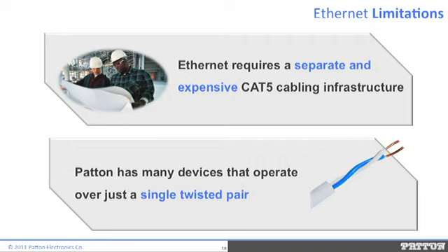The second, which is no small task, and I believe Nathan talked about it a little bit earlier, is Ethernet is not able to operate on the same cable plant. Most other legacy communications equipment was operating over plain old telephony grade wire. Ethernet really requires Cat5 cable or greater to operate properly. A minimum of 2 pairs is required for standard Ethernet data, and 4 pair if you run PoE Ethernet. The cost of rewiring the cable plants and changing wire topologies is a big consideration to companies trying to make this migration. We get this every day.